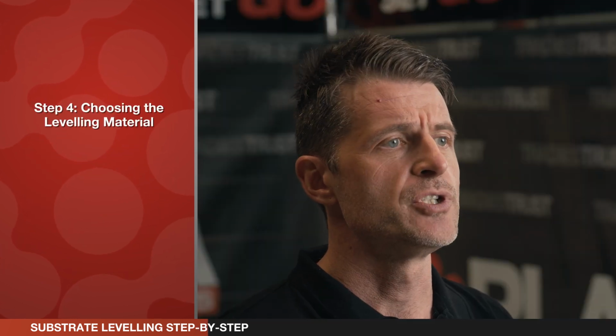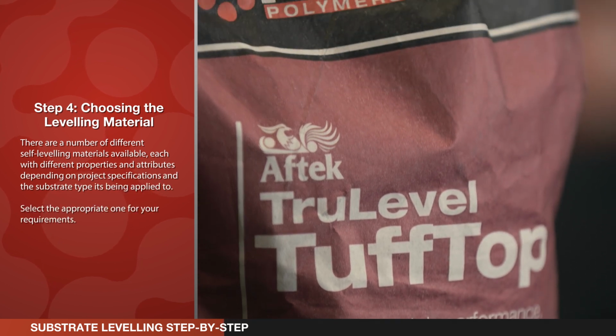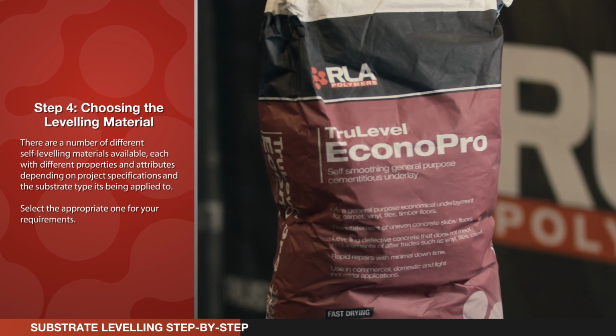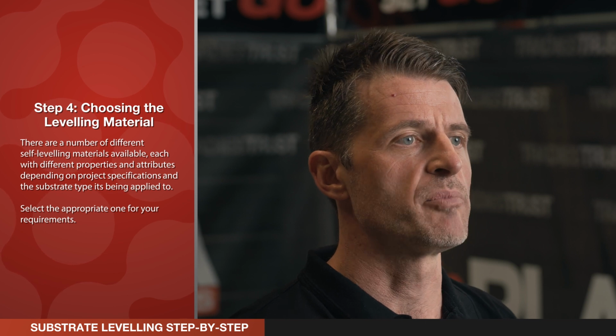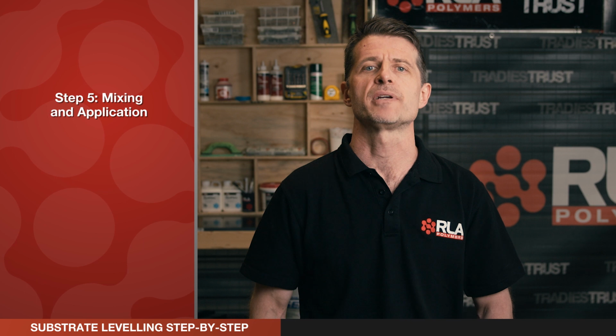Step 4. Choosing the leveling material. As mentioned previously, there are a number of different self-leveling materials available, each with different properties and attributes depending on project specifications and the substrate type it's being applied to. Select the appropriate one for your requirements. Step 5. Mixing and application.